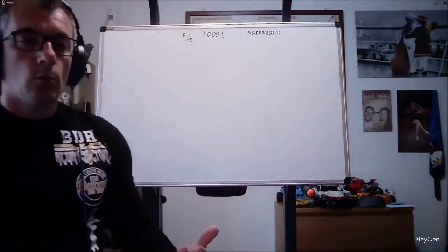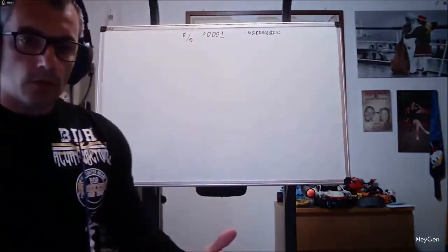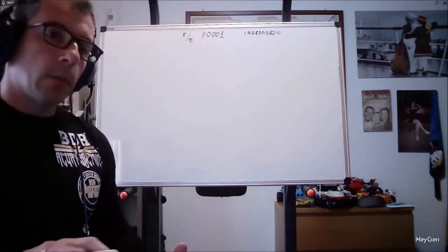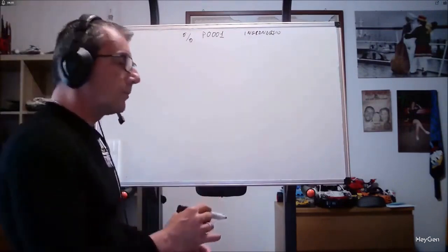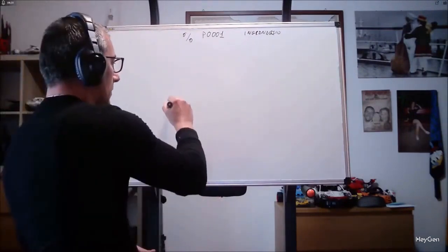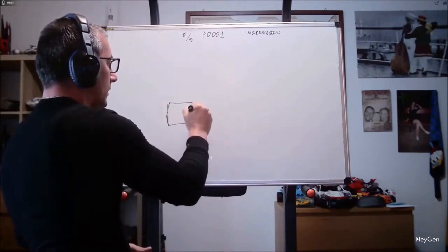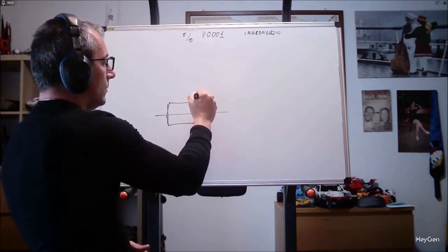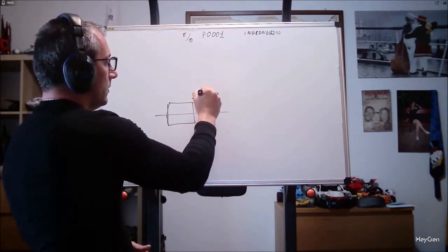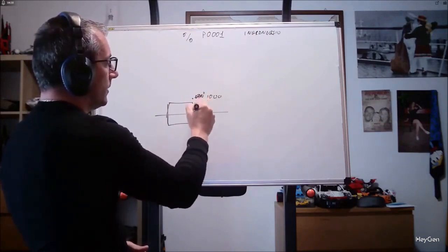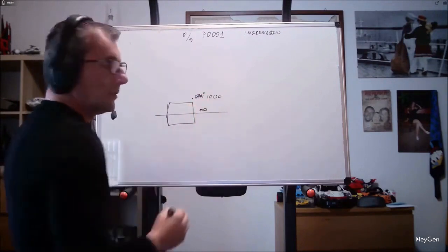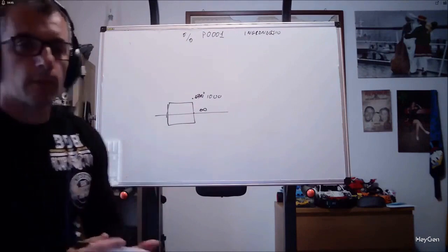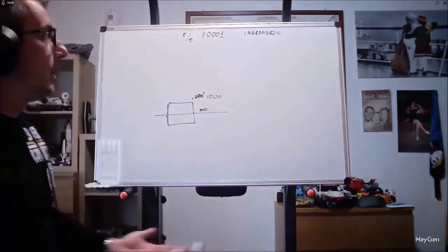It is good practice to always set a limit on the RPMs, because then we get into the details of cutting speed and fixed RPMs. But when working at a constant cutting speed, if this is our part and we are going to turn it, this is the center of rotation. If we have a speed, an RPM of 1,000 here, as we get closer to the center, we will tend to infinity. Obviously, we cannot run our spindle at infinite RPMs nor at 10,000, because otherwise we would have the machine shaking in the workshop.